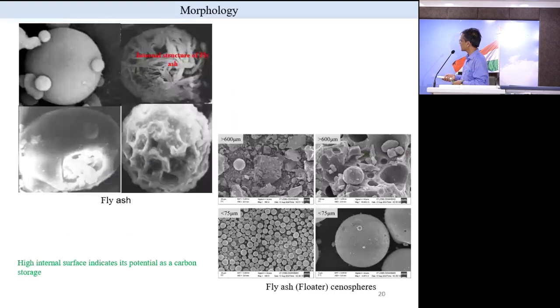So this you see is morphology, that is fly ash, very spherical of different types. In fact, once out of curiosity I burned it; fly ash was like this, spherical and hollow. Then I put it in acid and found what is inside. So that way you will see, when the particles are spherical, what will happen? You know the void ratio will be higher, because that will not fill in properly. What do we know? Angular sand is better. So that is the problem.